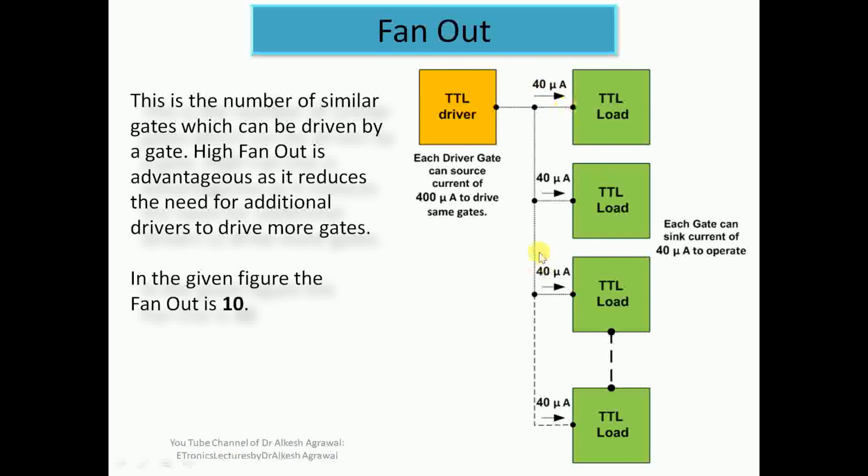If you equate both the source current and the sink current, with the maximum capacity of 400 microampere it can drive 10 such gates. We calculated 400 microampere upon 40 microampere. So in this particular figure, the fan out comes out to be 10.